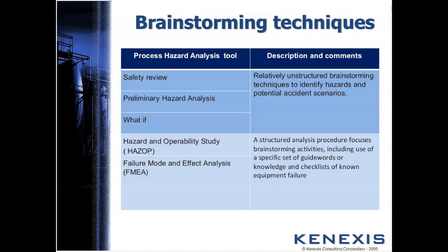A what-if checklist analysis combines the creative brainstorming features of the what-if method with the systematic features of a checklist analysis. For example, the checklist analysis is an experience-based technique, and the quality of the hazard evaluation study performed is highly dependent on the experience of the checklist authors, okay? So if the checklist is not complete, then the analysis is not likely to address the hazardous situation.